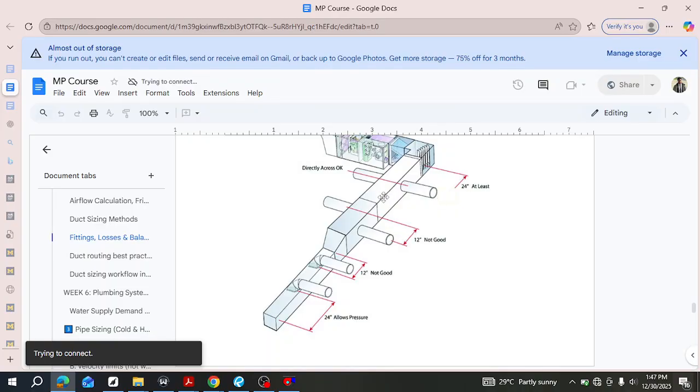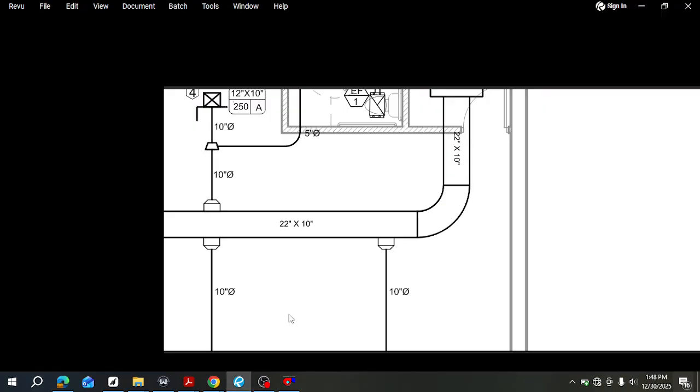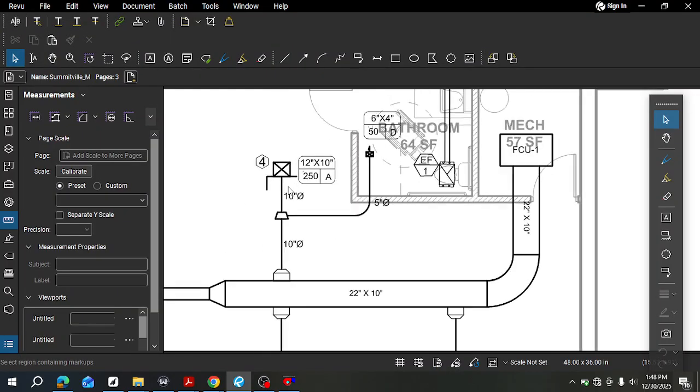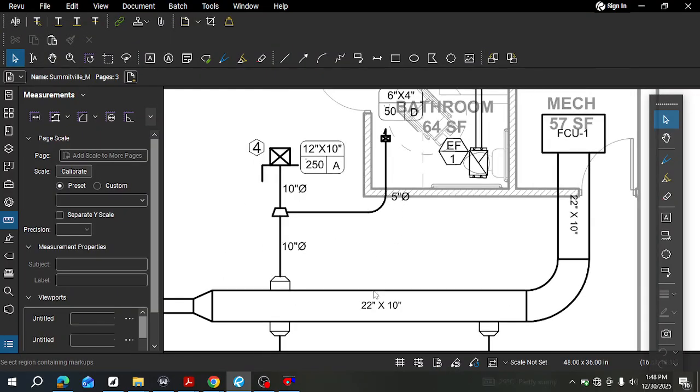Sometimes you can even decide, as you're branching off, instead of branching off close by, to branch off this branch. That usually has less effect because now you're talking about only the amount of air in that space. Something like this, right? I could have easily branched off here again, but fewer branches. So instead of that, I just took it off here and supplied here with it instead.